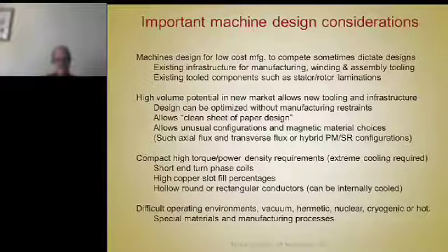Sure, they have very high torque density. They have a lot of wonderful features going for them, but nothing about the components or the manufacturing is like any other motor, so they're not standard. It requires all new tooling, all new infrastructure, and new assembly methods and everything. They have a whole different set of problems. So just because they have a higher torque density than a radial gap motor doesn't mean that they're guaranteed to be successful. And it's a manufacturing infrastructure that's really killed them, I think.